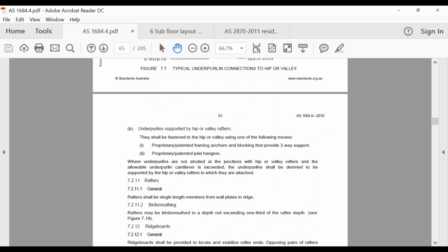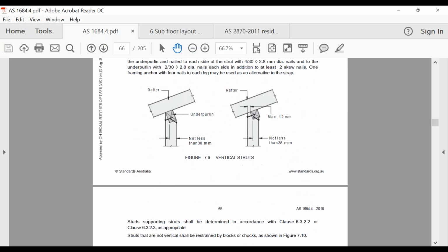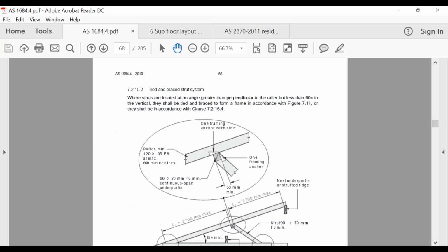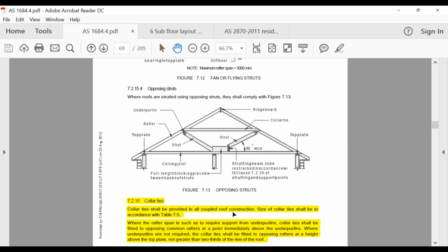One thing which you probably also get in a multiple choice is talking about collar ties. So I'll just scroll down to it. Sorry, next page. So this one is talking about a collar tie. The collar tie is that thing there in the middle, guys, and what it does, as the roof load gets pushing down, it sort of stops that ridge dropping and spreading out.